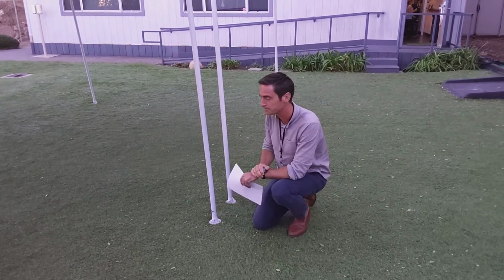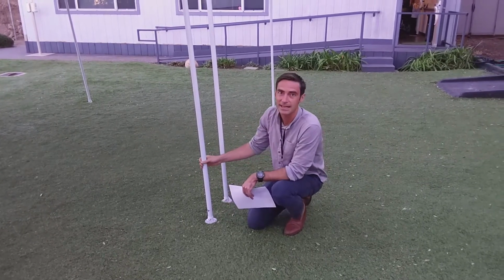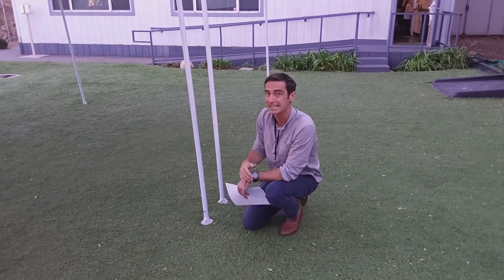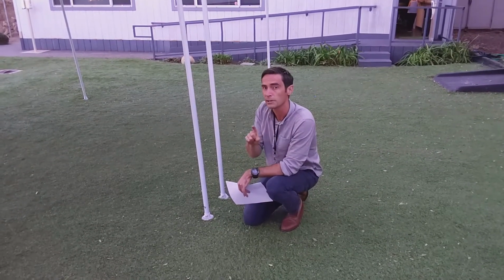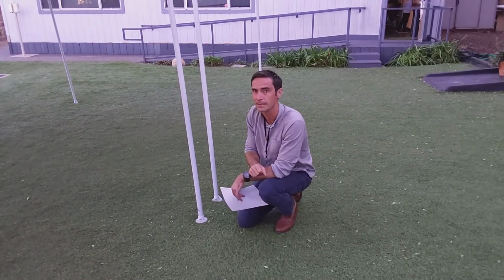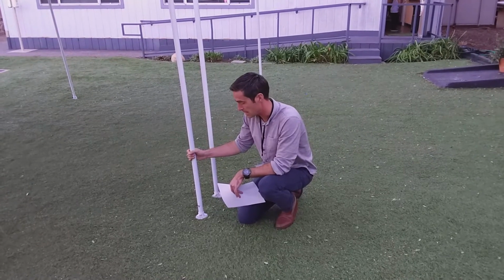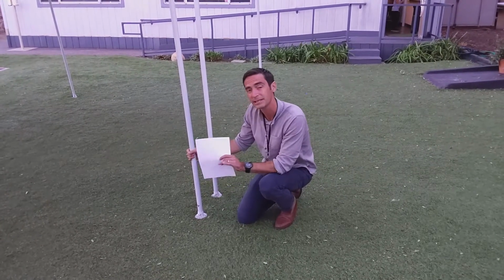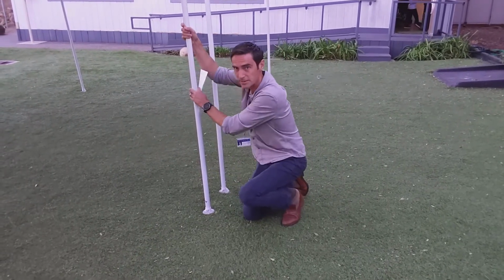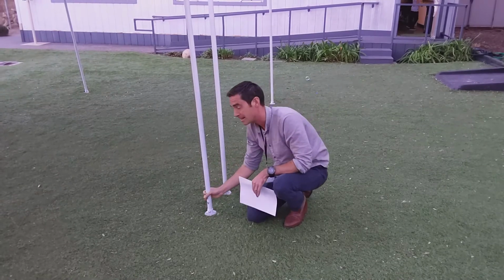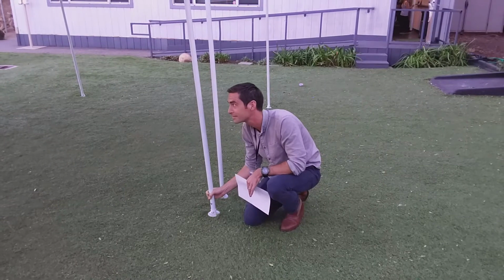It is simply supported. And this simply supported joint actually has 6 degrees of freedom, like everything, but only one of those degrees of freedom experiences constraint. Okay, and in this case, the only thing that it can't do, the only constraint it has, is the vertical. This thing cannot press through the ground, even if I pull down on it. Now, it can slide left and right. It can slide forwards and backwards.